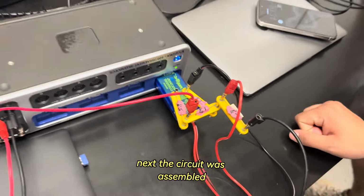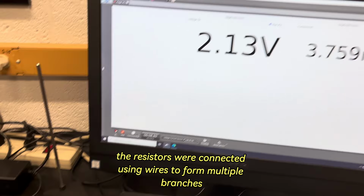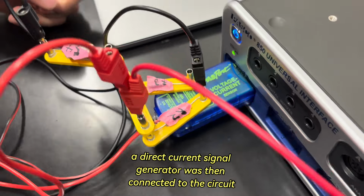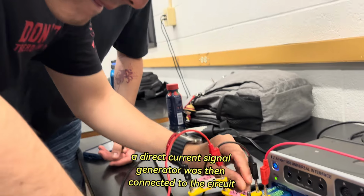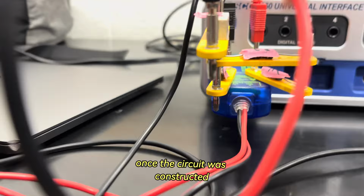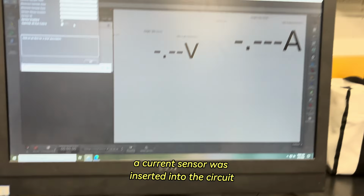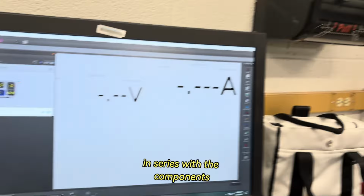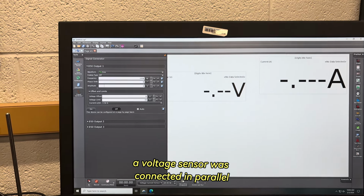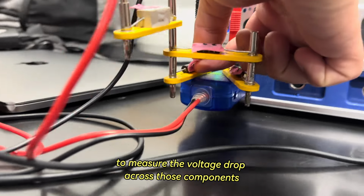Next, the circuit was assembled according to the diagram provided in the lab instructions. The resistors were connected using wires to form multiple branches and meet at junction points. A direct current signal generator was then connected to the circuit to supply energy. Once the circuit was constructed, measurement sensors were installed. A current sensor was inserted into the circuit in series with the components being tested to measure the flow of current. A voltage sensor was connected in parallel across individual resistors to measure the voltage drop across those components.